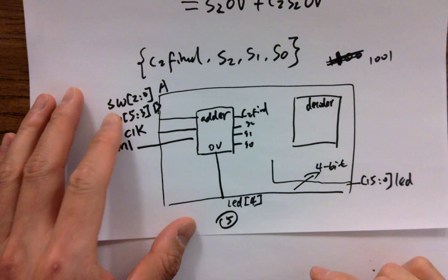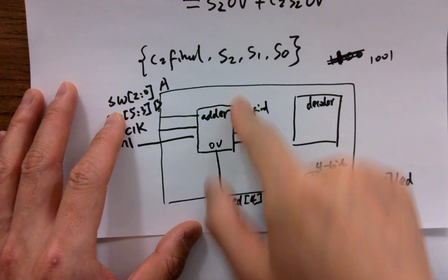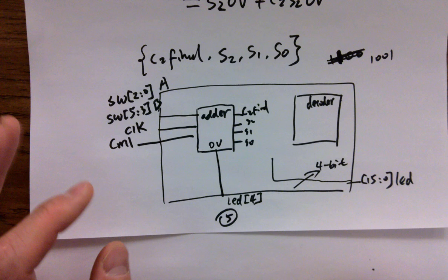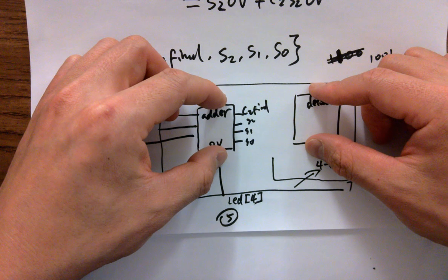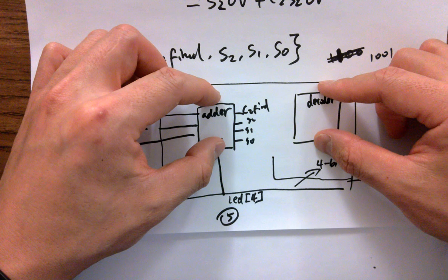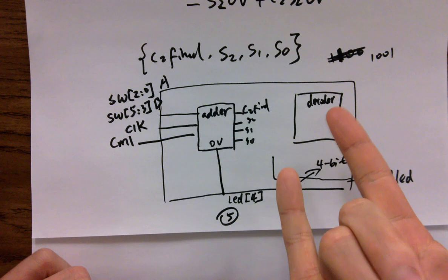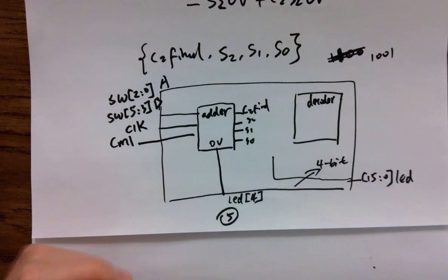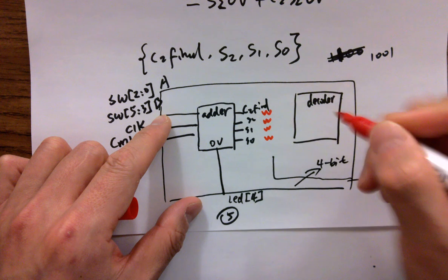However, I find out, hey, the decoder needs 4 bits, and LEDs also need the 4 bits. What are the techniques we have learned to deal with it? Always thinking about coding, right? When you're writing code, how do we do that? So eventually you are having two sub-modules having an interconnection. The only way we can do a connection is with the sub-module in the top, right? We do a dot something parentheses to make the connection. But now, in between two sub-modules, we need the interconnections. What are the techniques we used? Wire, yeah. It's gonna be a 4-bit wire.